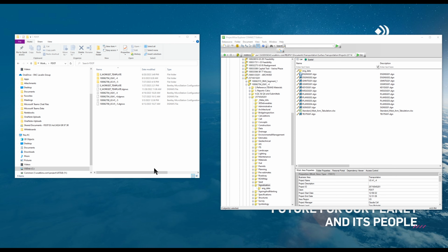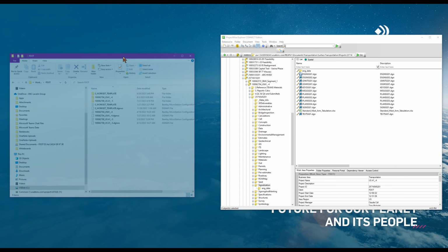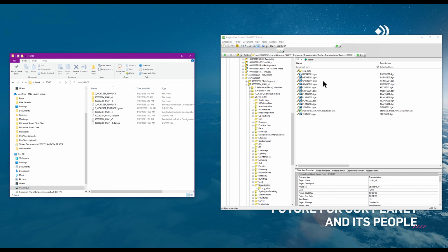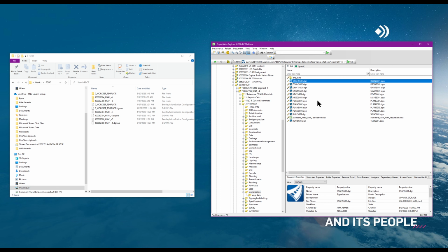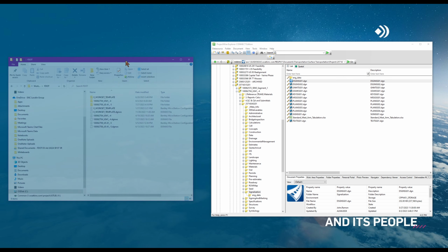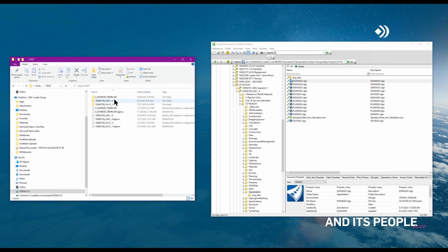The first thing I want to say is, as usual, you cannot run Takeoff Manager while you have a file running from ProjectWise. You have to export it locally so you can run Takeoff Manager. But you can actually design your stuff while you are running from ProjectWise and then take your file back to your local drive, run Takeoff Manager, run ORD locally from a file that's coming from locally, and then get your Excels in the calculation folder